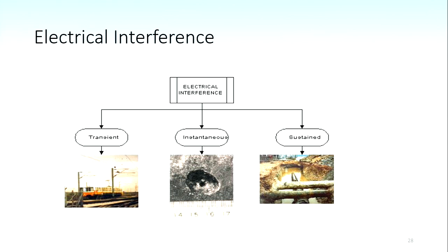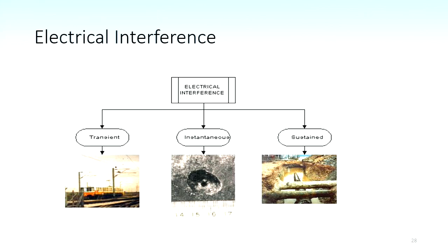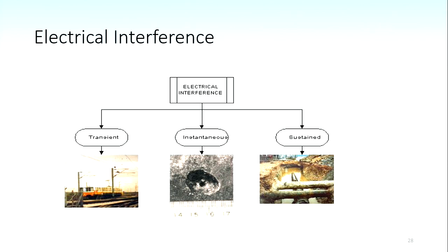So this electrical interference affects the potential of your pipe? Yeah. So here's a bit of pipe with a pit in it as a result of having lost the potential control. So basically, the potential of your pipe changes, resulting in additional current being supplied. It may not be additional, it may result in less current being supplied because current has gone off to interact with another pipe.